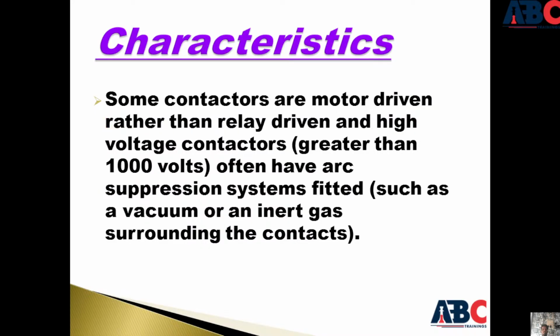Characteristics: some contactors are motor driven rather than relay driven, and high voltage contactors greater than 1000 volts often have an arc suppression system fitted, such as a vacuum or an inert gas surrounding the contact.